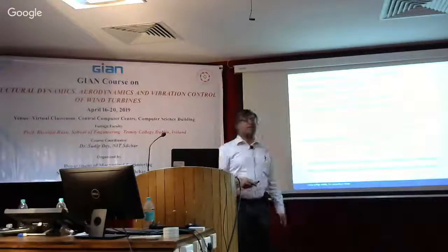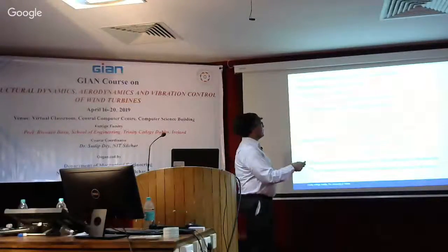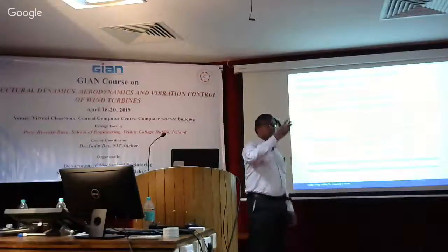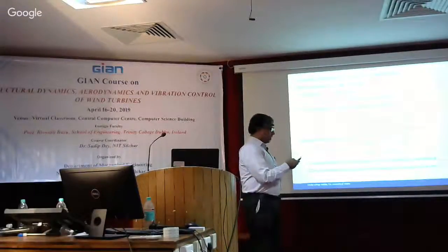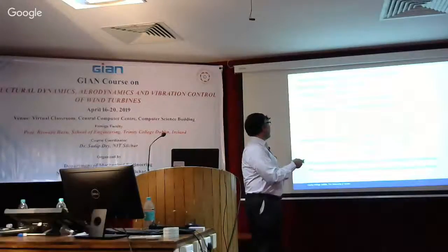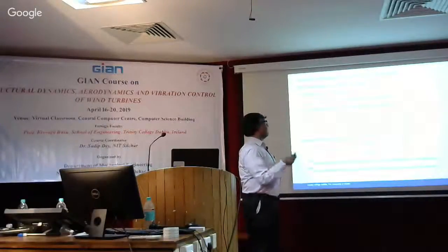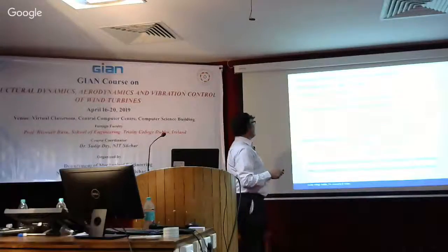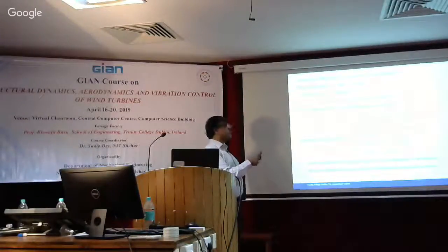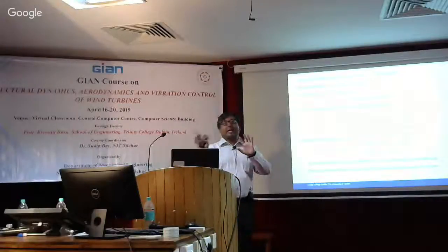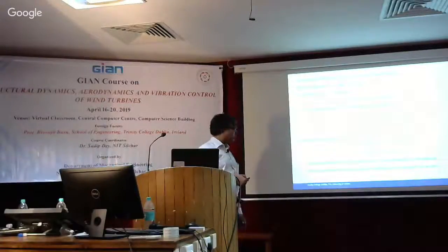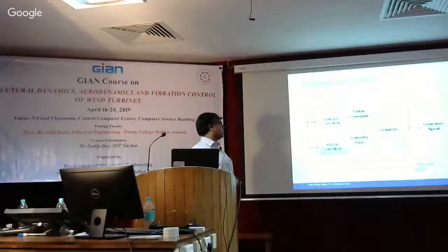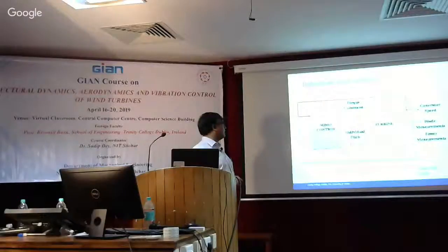So the 3 pitch angles will have to be controlled, and there are certain relations between the 3 blade rotations as well. So you could connect the 3 in some form, and then by your transformation, design the controllers so that they work collectively or individually. That means all the 3 will have some coordination, or they can act separately as well. This is just a schematic to show how this collective pitch control works with top controller and so on.